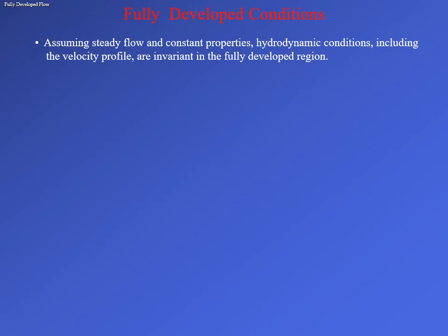And again, the discussion we'll do now will be for fully developed conditions, because in the developing region things are not as stable as for the fully developed conditions. And again, if you are talking about a very long pipe where you are doing the analysis, the entrance length will be some initial part, and beyond that the flow will be fully developed. So it's more useful to understand the fully developed conditions correlations than the entry length, because the entry length region is only a small region in the beginning.